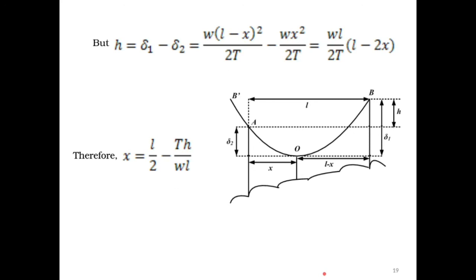Yes, more tension at the top, meaning the person standing at the top will have to pull it with more tension, meaning we have to ensure that we have more pulling force here. That's the first thing. Second thing, when we say more tension at the top, we need to again go back to the working tensile and tensile strength of the conductor.